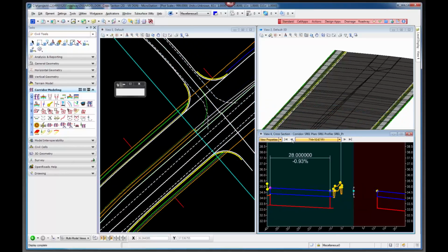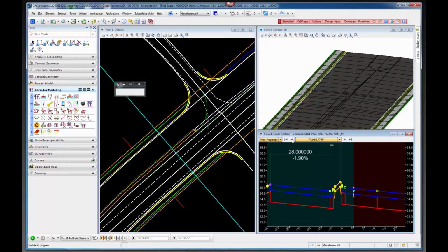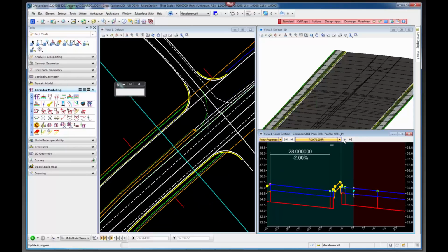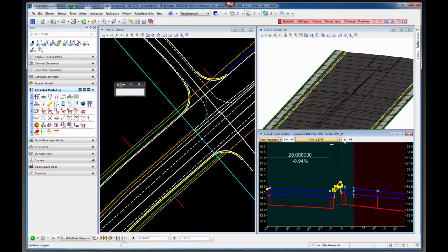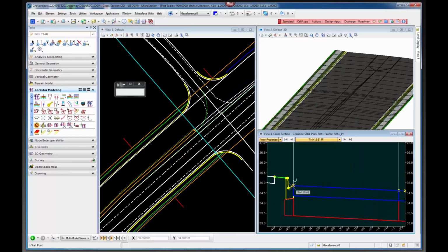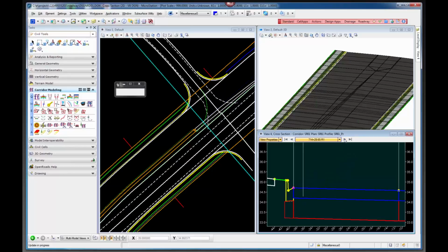Now you can't do that. Well, it looks like this is where the super elevation was still in transition. So the super elevation control is what overrode even my parametric constraint in there. You'll notice that there's a red magenta box on this point. That is a point control, which is the super elevation control. And then as I get in here and the super elevation transition limits itself, it should change to a green box.